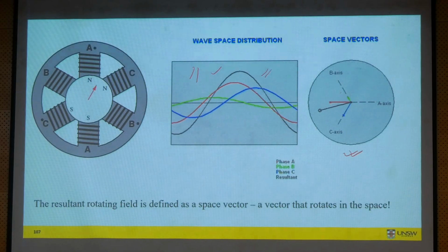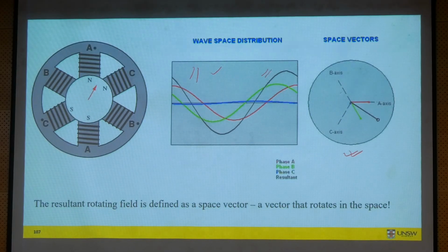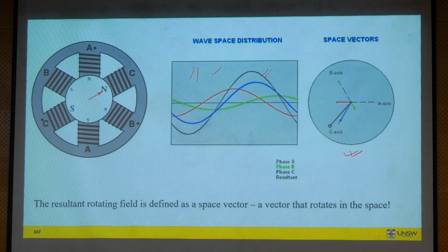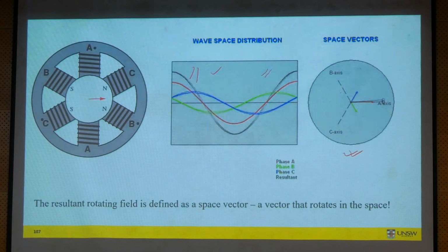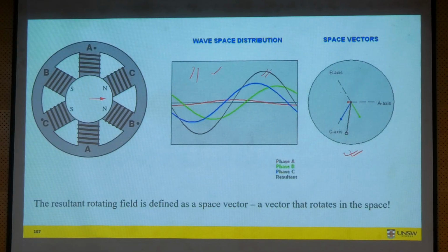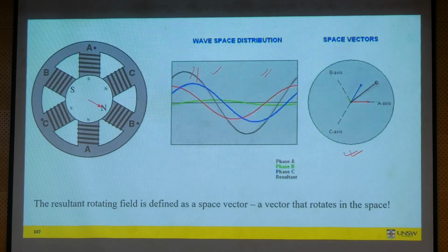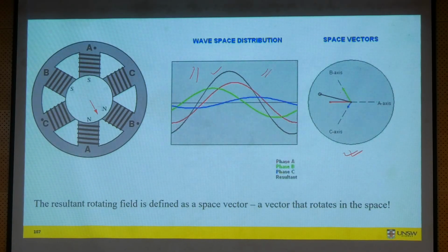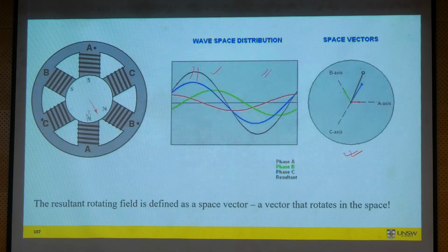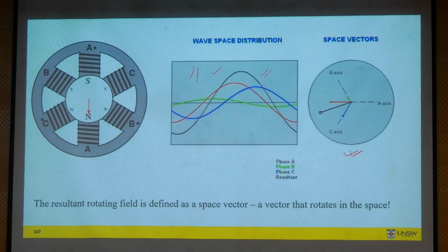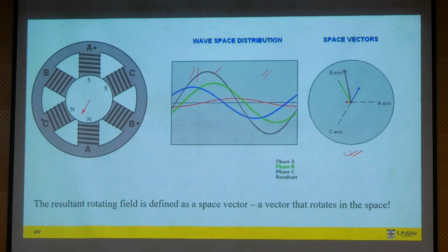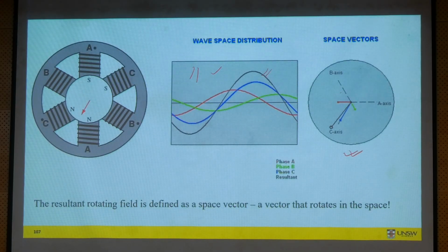So it could be voltage, it could be flux, the space vector, or it could be even MMF. In the concept like DTC, direct torque control, you in fact try to produce this space vector by switching your inverter in such a way that they give you a particular space vector for a particular torque or flux. Okay, that's how is actually DTC. Okay, so it comes from this very basic concept.